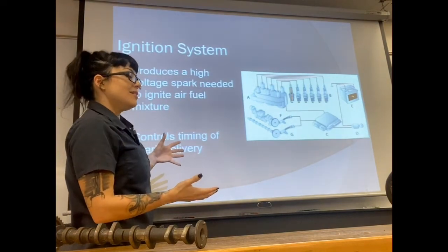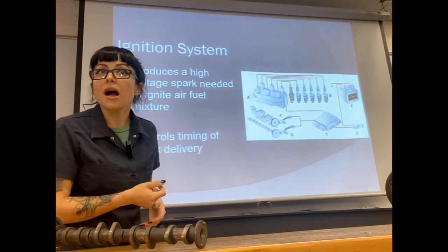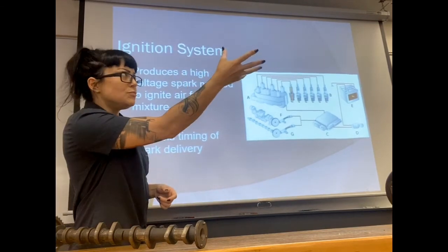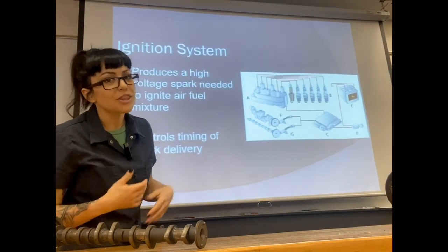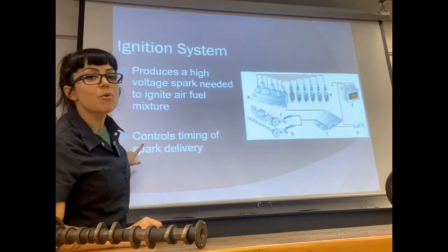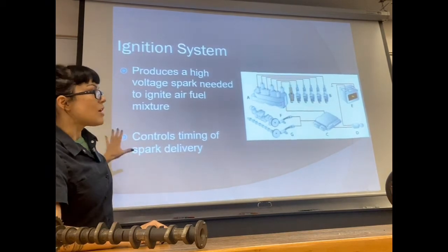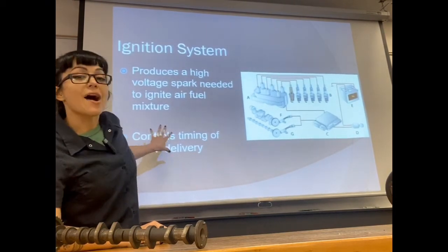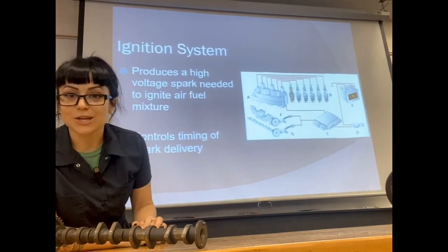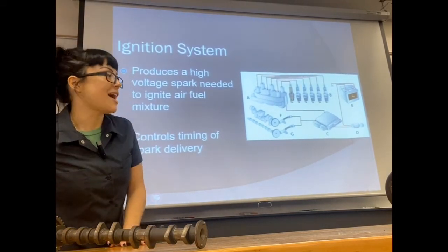Here's the deal. It needs to be timed properly. If I ignite while I'm trying to let go of exhaust gases, that doesn't help. Or if I'm just at first taking in air and fuel, that doesn't help either. It needs to be right when it's squeezing it. And so it's really important that our ignition system is doing this in the proper timing as well. We've got a whole section and lecture on how we do this, different types of timing systems, different types of ignition systems, mechanical and electrical. So I'm really excited about getting into that.